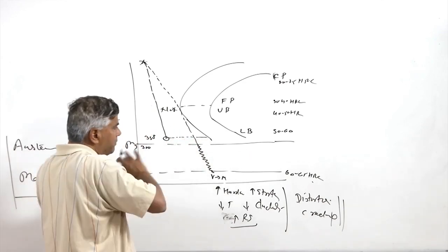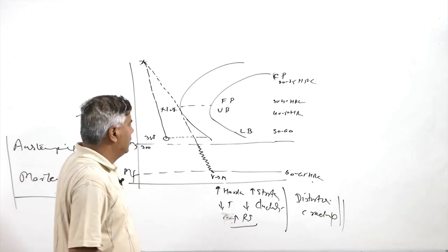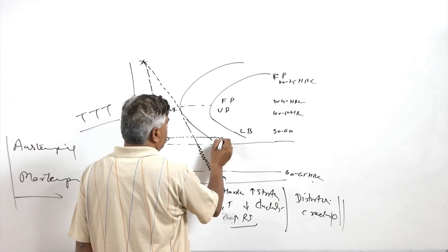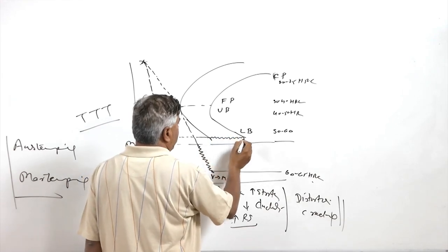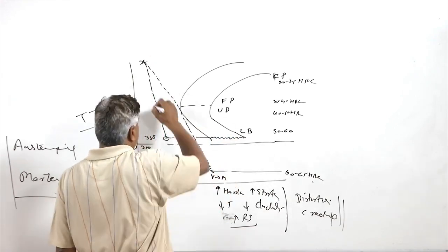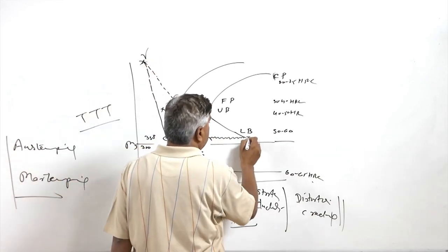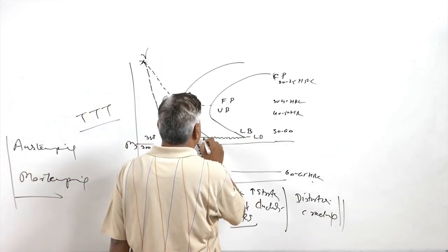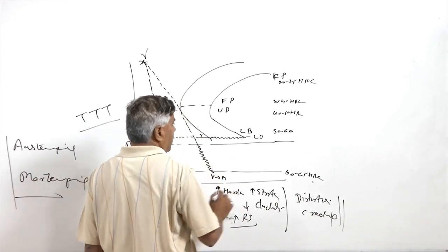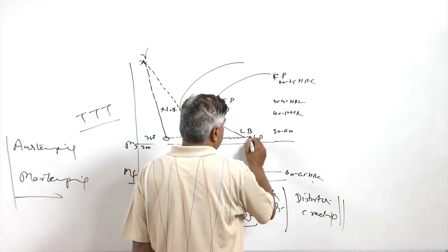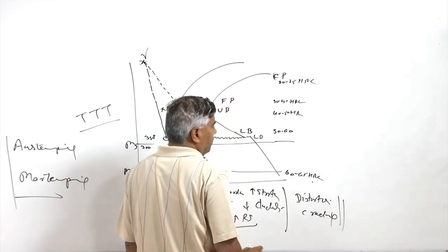So the whole section will be homogenized with regard to the temperature, and then it will be transforming into the lower bainite. So austenite transformation to the lower bainite occurs in case of Aus tempering, and thereafter once this transformation is complete, it is cooled down to room temperature.